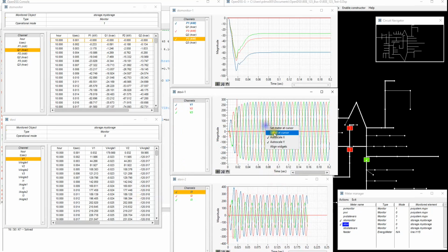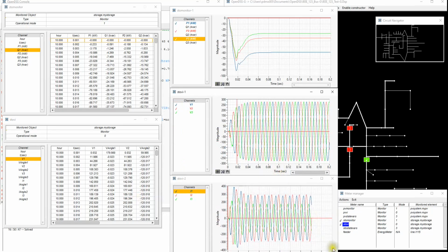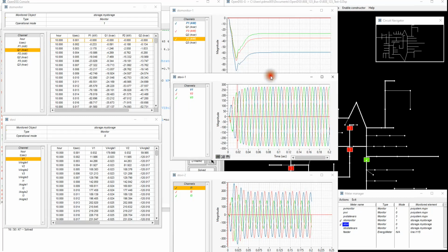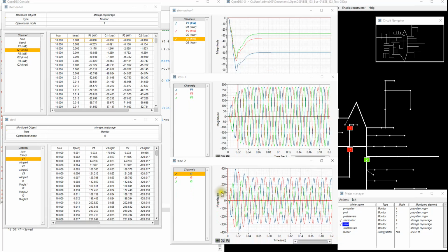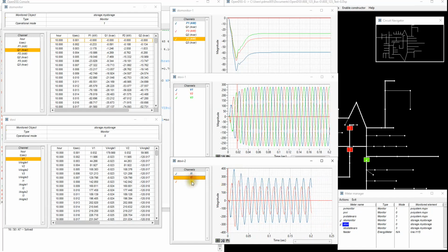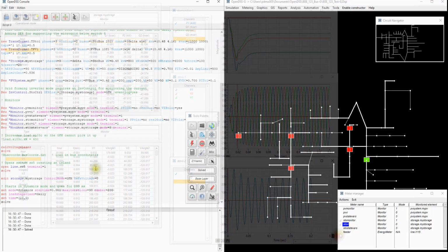For instance, the current waveform matches with the power QSTS widget that is basically telling us of the peak demand at the beginning of the black start. Then we will see how the current basically gets lower given the entrance of the PV system. The interesting thing about these representations is that you can have a very good approximation of how the waveforms will look like in the time domain using a frequency domain simulation like the one that happens in OpenDSS.